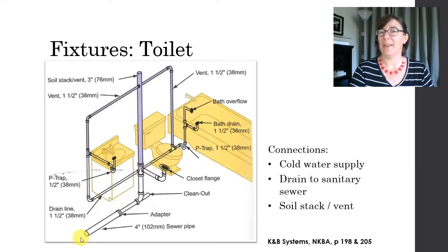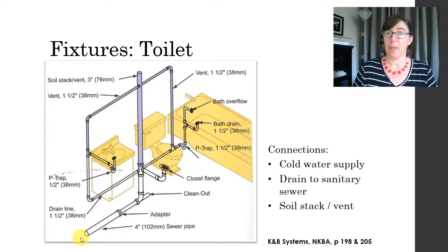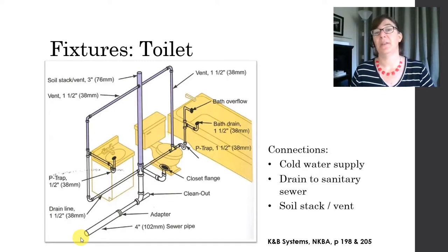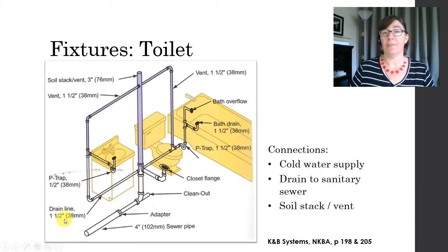Connections. What does your toilet need to be connected to? It needs a cold water supply, and it needs to drain to the sanitary sewer. It also needs what's called a soil stack or a vent, and that can be shared with other fixtures.